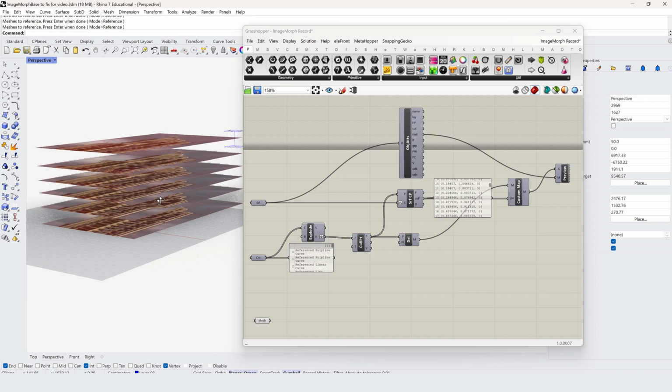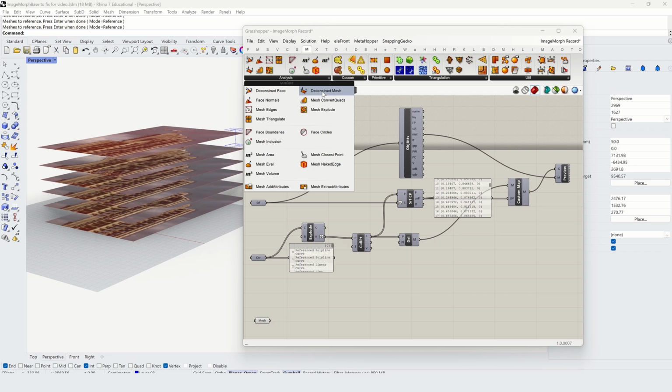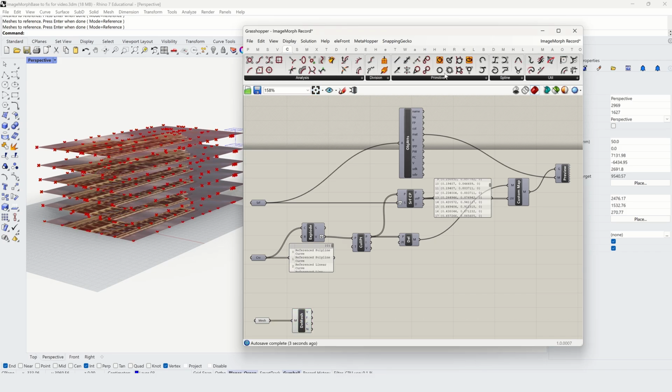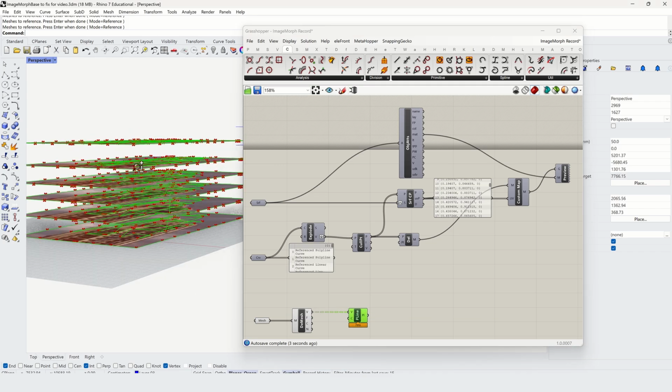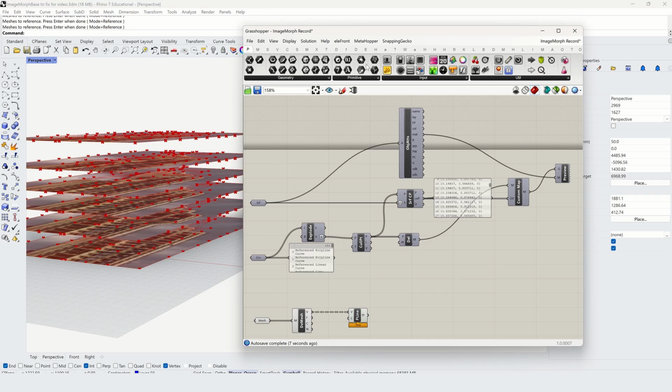In the same way that explode curve was used to extract the component vertices of the curve, deconstruct mesh outputs a mesh's component parts. Creating polylines from the vertex outputs gives the opposite effect, however, tracing one curve through every point in a mesh for every mesh rather than across the meshes. This is the impact of the tree structure again.